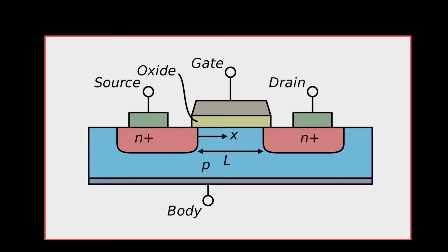That's going to reduce the depletion region, allow a bit more current to flow, which allows the drain to reduce its voltage, which allows this to open up even more. And so you see it drives it. You've got a nice positive feedback cycle here, where as the channel opens up, it becomes even easier for it to open up further, and hence the inverter works.